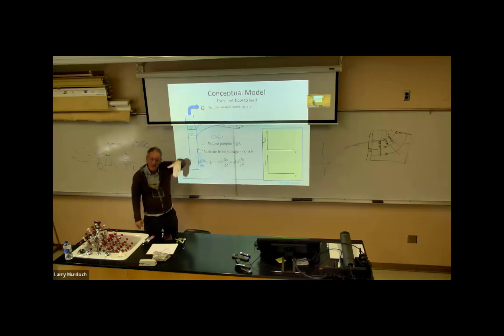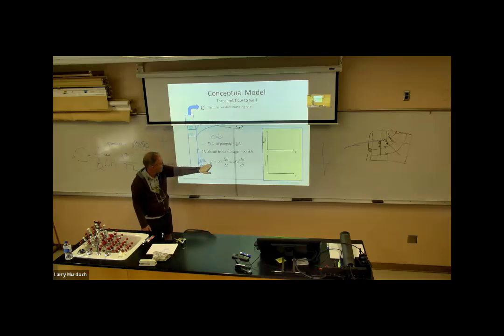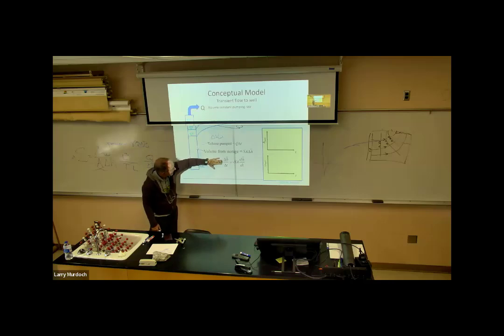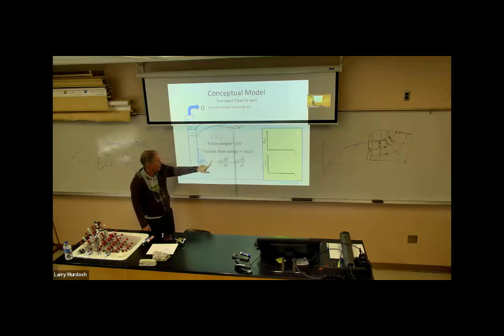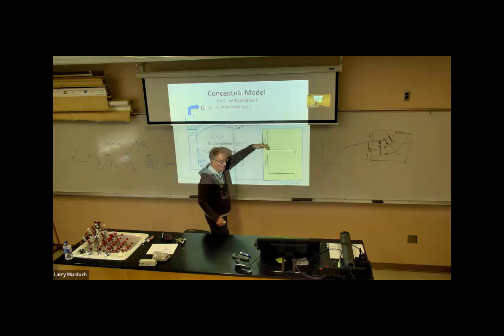Okay, the head is dropping, and that's releasing water from storage. So when this is positive, that has to be negative, and the minus sign then flips the sign, so that side is positive. So we drop the head, we produce water from the well. So we see that the head in the well is going to be dropping.